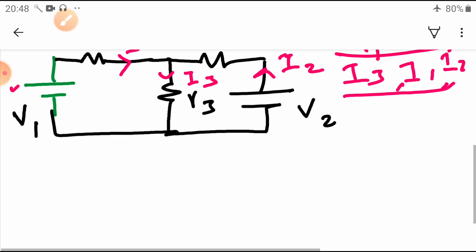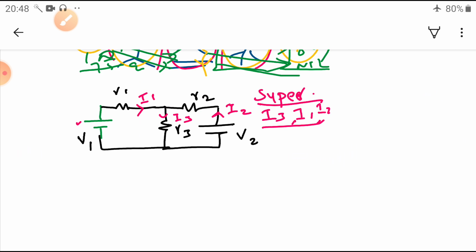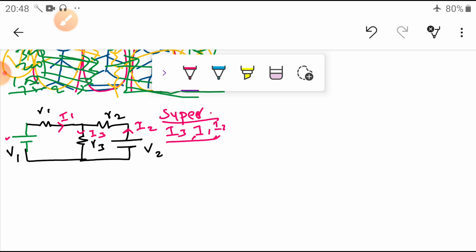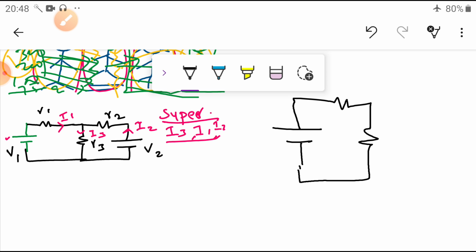Then what we have seen here, this is the source given. In the first case, I connected only V1 and the resistances. All network elements that are passive elements are the same, but only the active element I took out. If an internal resistance is given, I would represent it here as a capital R. Here no internal resistance is given, so I simply shorted it as per the basic theory.